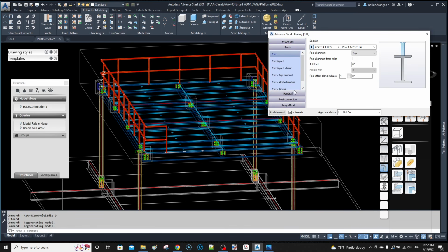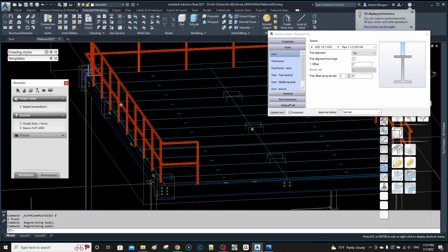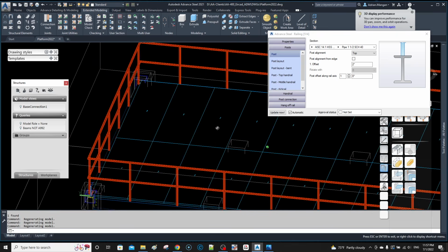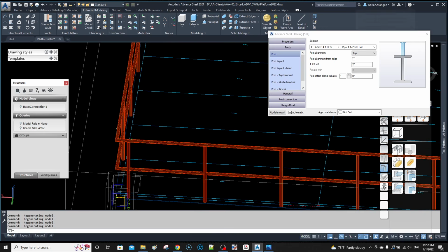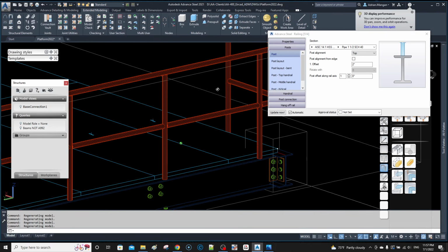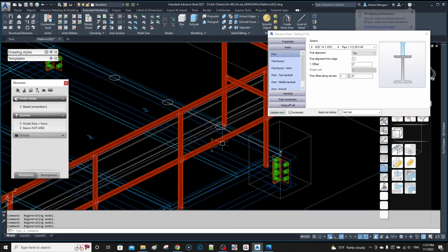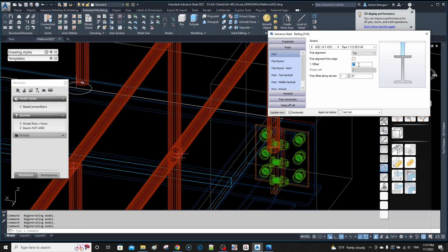So let's just see posts, post alignment, top, post alignment from edge, offset 2 inches. Now, hopefully it's offset them all out. It doesn't always, as far as I know. Yeah, it did. I thought this last one might have been offset in. No, it should offset in the right direction. Maybe I'm just not remembering correctly. Now, it's a little near to the edge, but might be okay. Maybe we'll change that to 1.75.